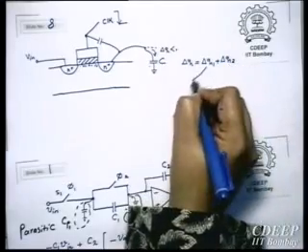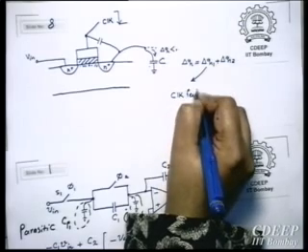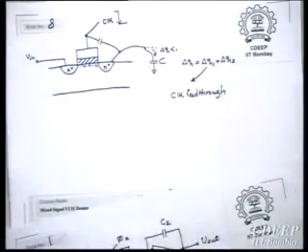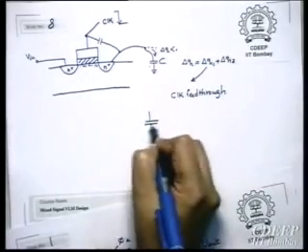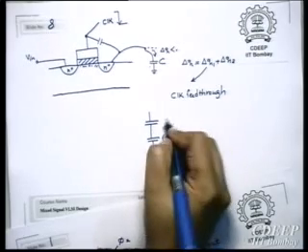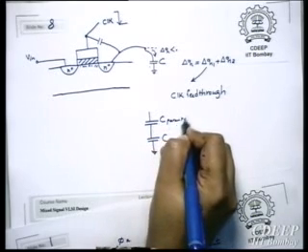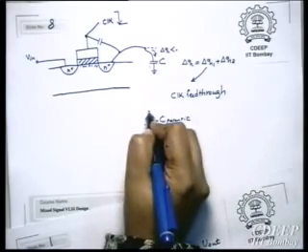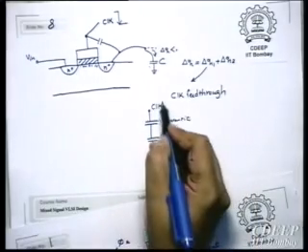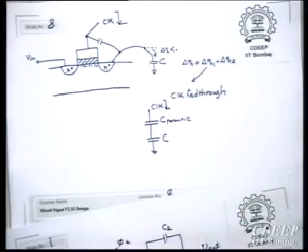This delta Q1 is due to clock feedthrough, and clock feedthrough is this capacitive division. This was C, this is C parasitic between gate and source, and this was clock. So a falling edge, if it is very sharp, will create a delta Q on the C.